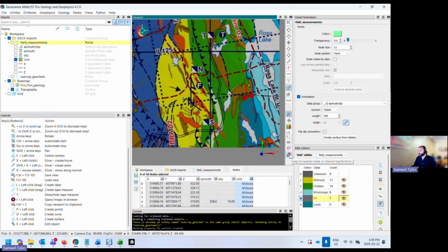There's a picture in the user guide that can explain it a lot better than I can verbally. So if we want to look at that in more detail, I can pull up that picture. But for now, you can test it for yourself. If you want to snap specifically to a drill hole interval, you'll want to turn this on. If it's not on, you'll snap anywhere along the drill hole trace.